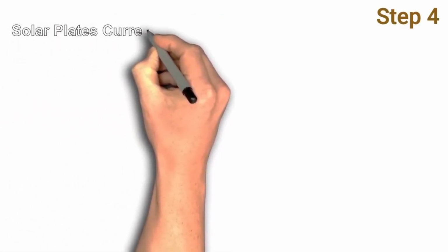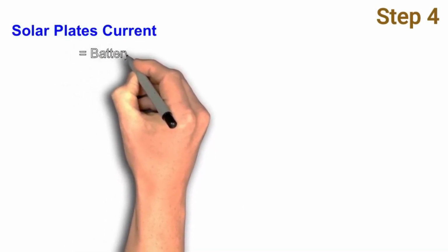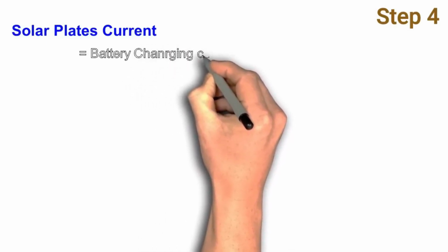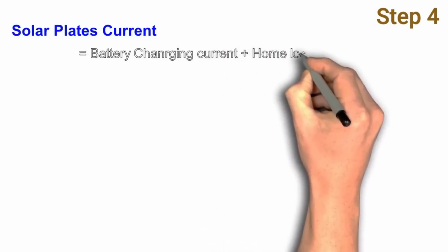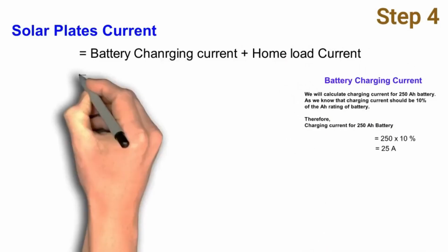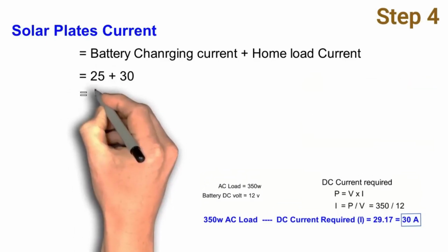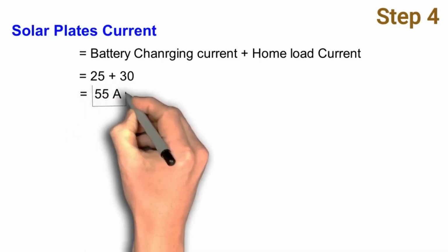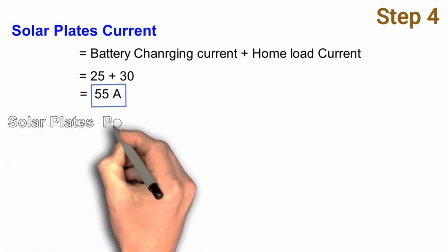Finally, we'll go over the home load calculation. This is a critical step to determine how much power your solar system should generate. Add up the wattage of all the appliances you plan to run at the same time. For example, if you have an air conditioner that uses 2,500 watts, a fridge that uses 300 watts, lights that use 150 watts, fans that use 400 watts, and other smaller appliances, your total load could easily be around 3,500 watts or more. Always account for any peak usage times, such as when the AC is on, along with other appliances to ensure your system is adequately sized.